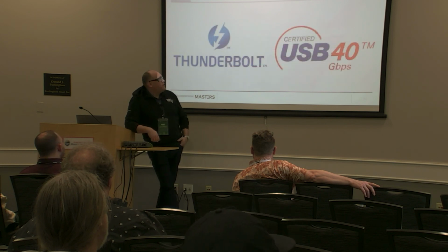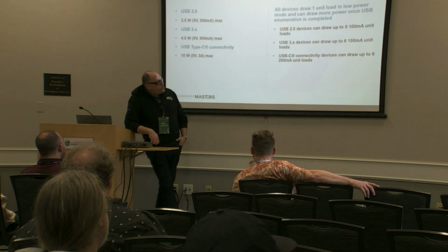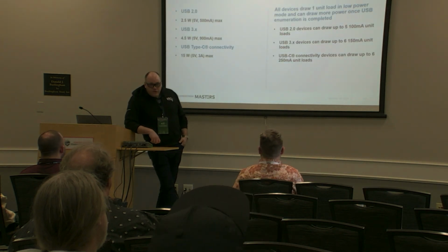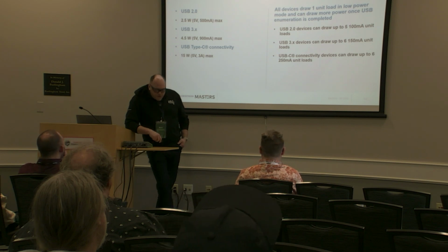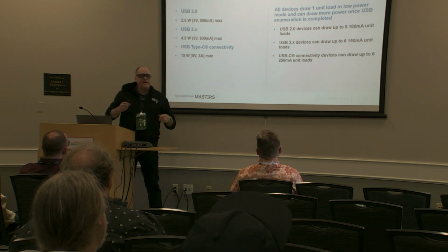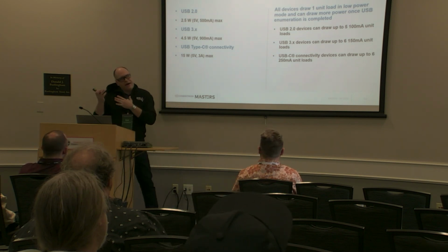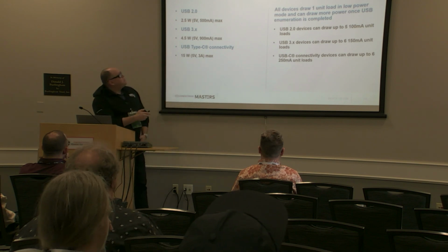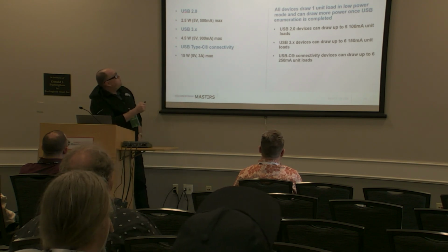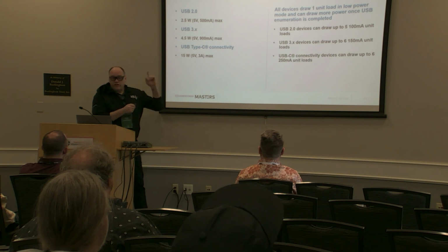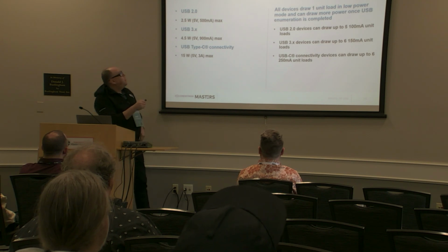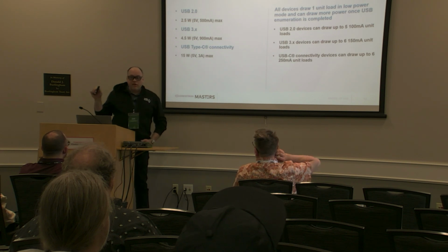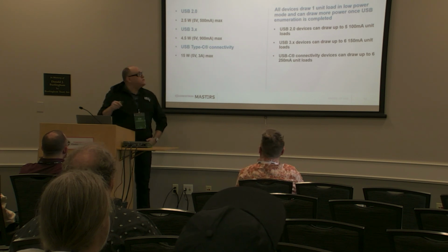Thank you. No problem. So shifting gears, let's talk about power. There's a lot more I could say here, but I'm going to breeze through it. How does a USB device get its power from the host? First, let's talk about what the specs allow. For USB 2, we've got 2.5 watts, that's 5 volts on that one pin, and it carries a max of 500 milliamps. That's the most power you can draw on a USB device.